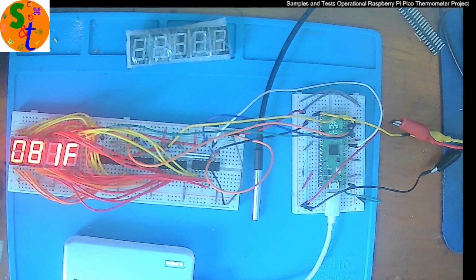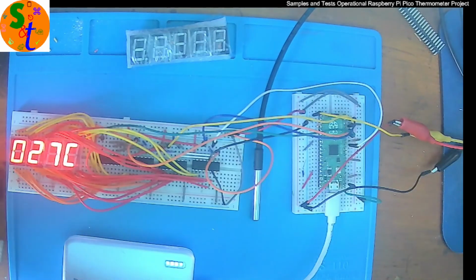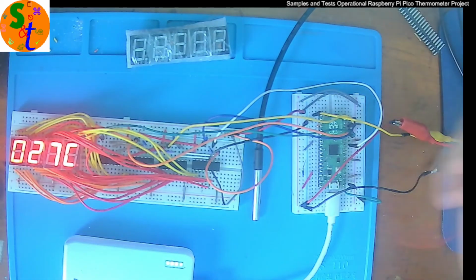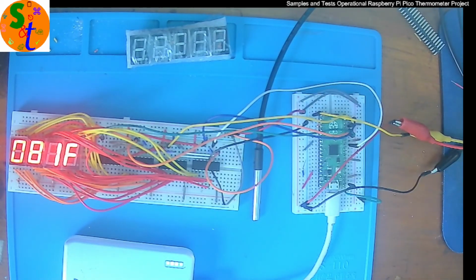And then I need to see how I'm going to power this. Am I going to use a USB power pack? Could I use a solar panel? Could I use a 9-volt battery with a voltage regulator? Actually, any of those besides the USB should have a voltage regulator. Can I use AA or AAA batteries? There's just a wide array of items that I can use.